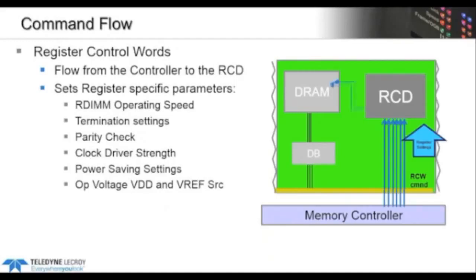They flow through the rank 0 DRAMs behind the register, but because it looks like an MR7, it's ignored by the DRAM. Okay, so MR7 is supposed to be ignored, but just by the DRAM. The remaining address bits, your 0 through 12, identify the control word and basically the payload of the RCW.